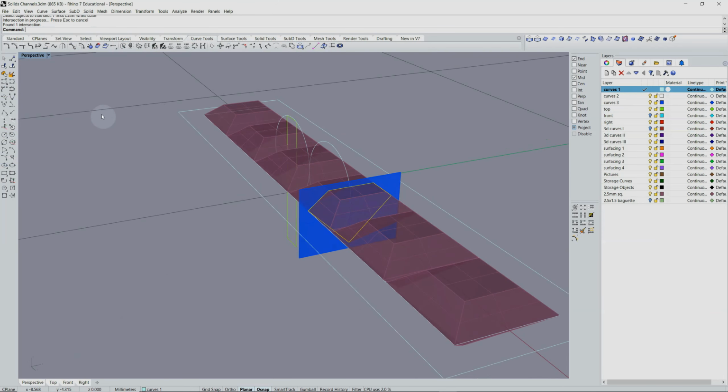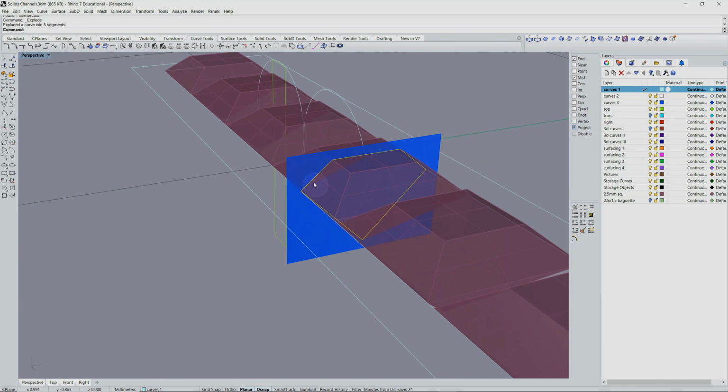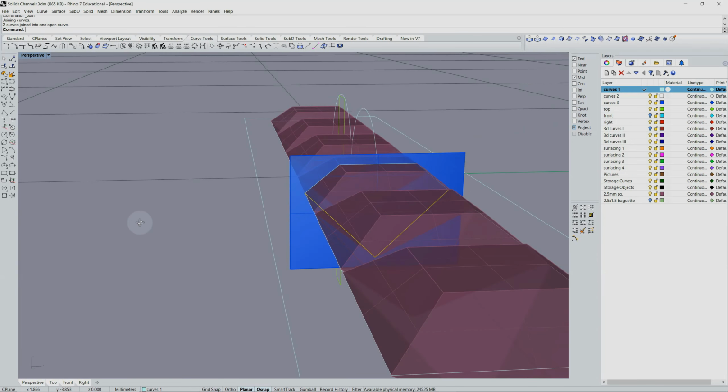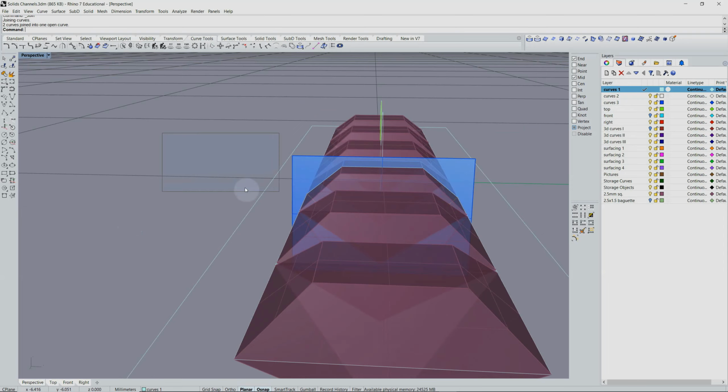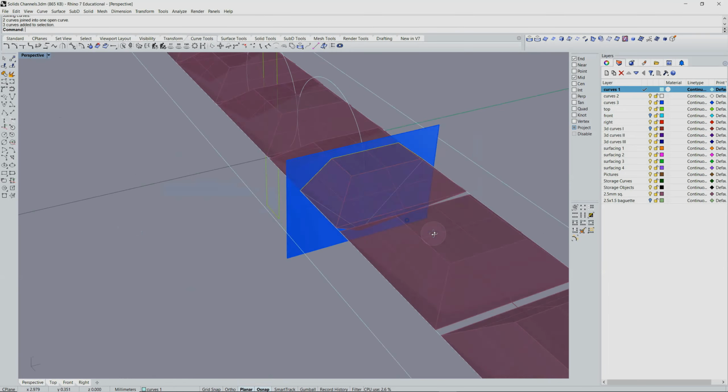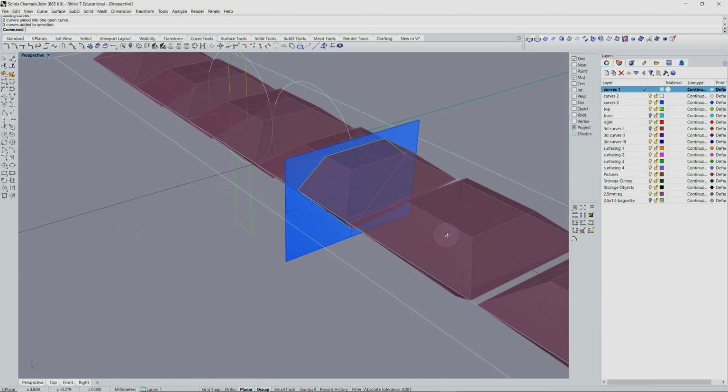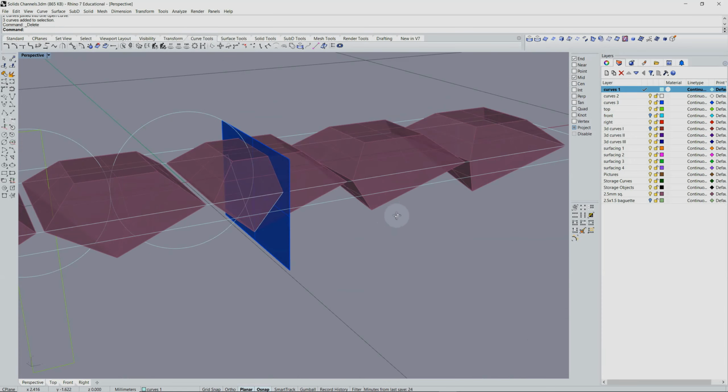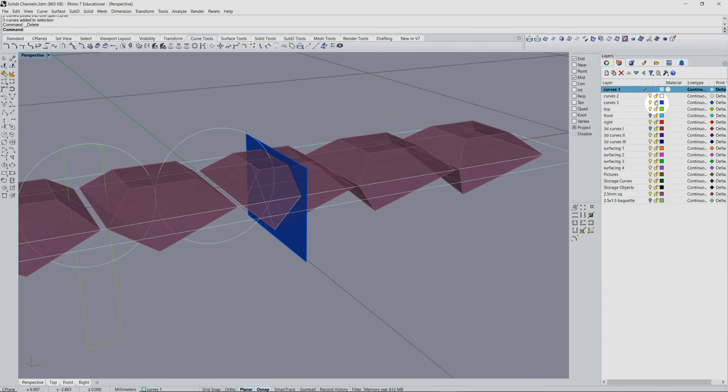At the end of the Object Intersection command, the intersection curve remains selected. Go ahead and click on the Explode command and Control-click on the three segments that form the crown and table portion of the intersection. Then hit Join to join together the two pavilion curves. Use the window selection to select the three top segments that we will not be using, and hit Delete. And then I'll turn off the Curves 3 layer that holds the cutting plane.